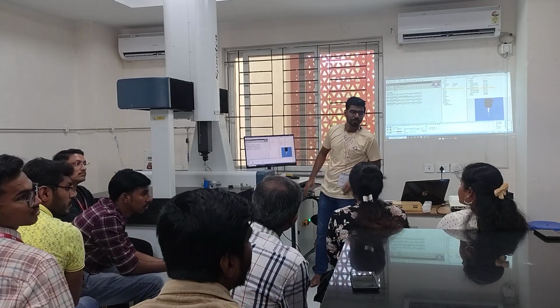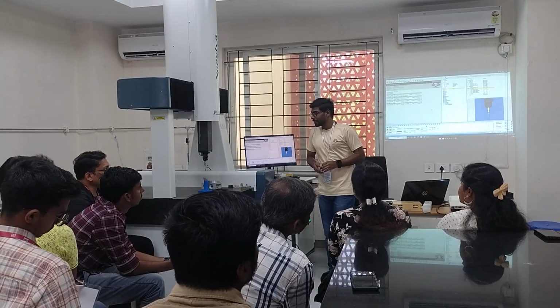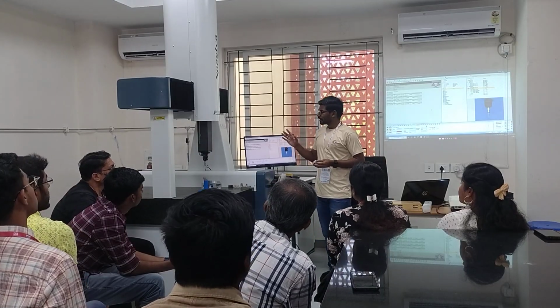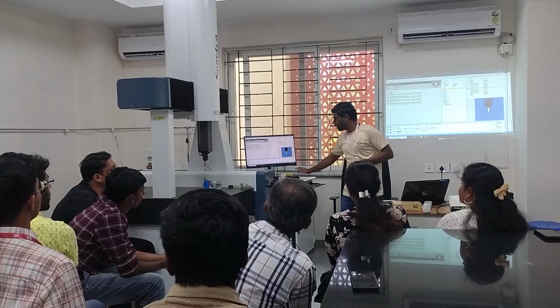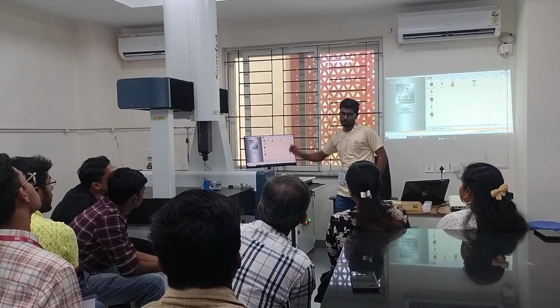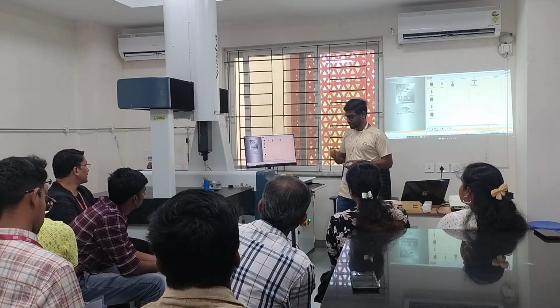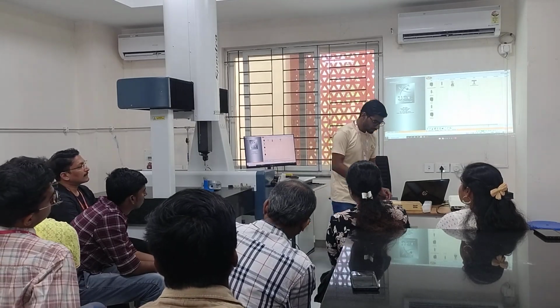There is no need to measure the origin whenever we perform this measurement. There is a homing option; when you use it, automatically it will go to home. So after that, there is no need for any kind of measurement. But yes, calibration is required.